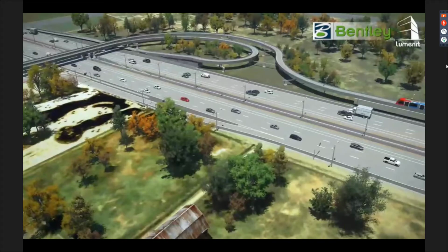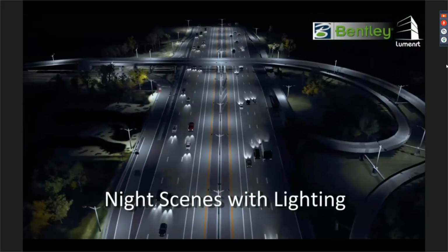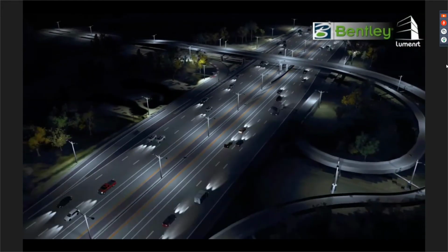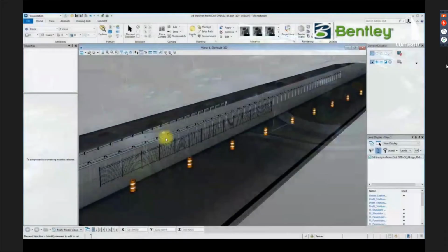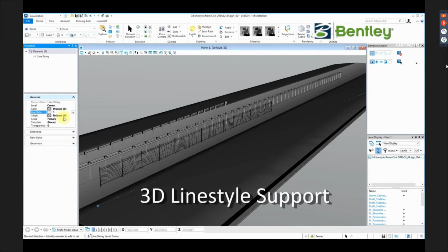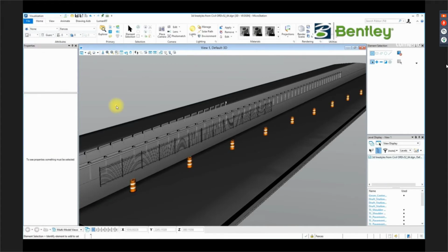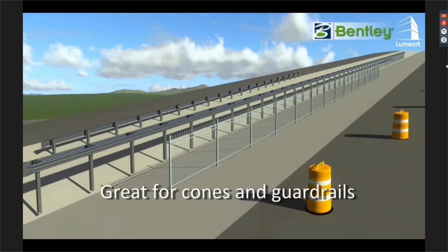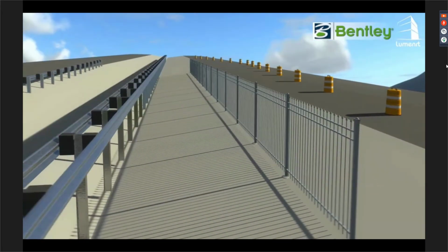So regardless of a model being road, rail, and depending on the scene that you would like to depict, nighttime, daytime, and even the location of your project. That's why from the very start, you have to make sure that you assign the right coordinate system, because the season or the time of the day can also be staged or modeled inside LumenRT.